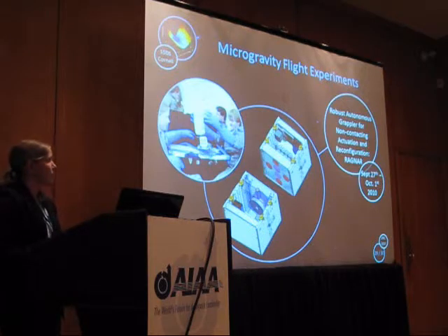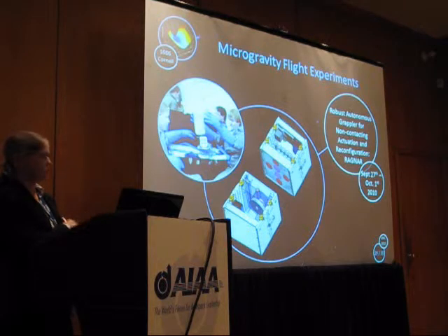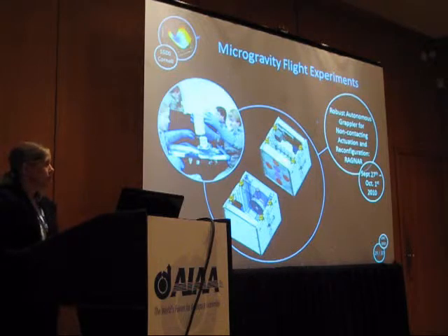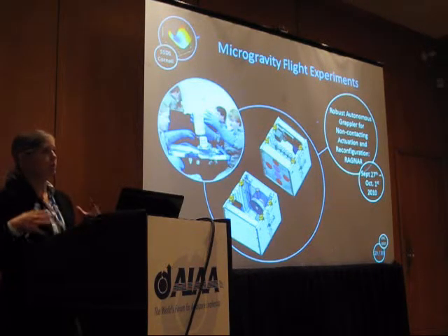We're building off work that we did last year. We flew a Flux-Pinned interface on a microgravity flight in the previous year, and that was a pure passive system. We just stuck the superconductors and the magnets on there and saw what happens. Whereas for this year's microgravity flight, which is going to be from the 27th of September through the 1st of October, we're putting a series of electromagnets on there, and we're going to be actively, autonomously controlling it on board.